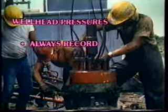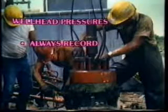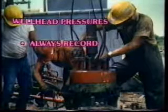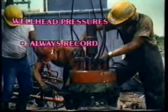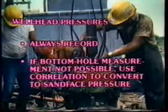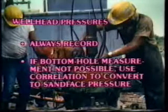We measure surface pressures continuously and have a deadweight tester at the surface. In some instances, for example, where there are mechanical difficulties, highly deviated holes or sour gas production, it may not be practical to run bottom hole gauges. In such situations, wellhead pressures are measured and correlations discussed in your manual are used.